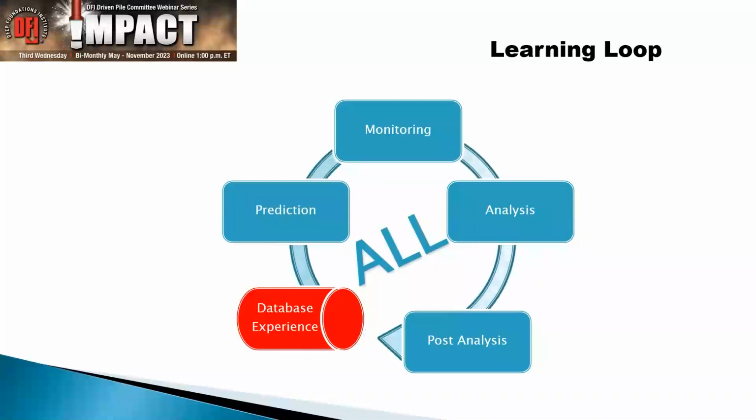Well, within Allnamics, we change it a little bit. We call it the Allnamics Learning Loop, but it's really nothing other than PDCA, but there's an additional step in there. And that is that red box that you see, where you now have your database experience. Basically, your plan is the prediction. Then you do it, and while you're doing it, you monitor your pile. Then you analyze those results. And you also do a post-analysis. You compare your assumptions before with your assumptions based on the analysis data, whether they're valid or whether they need to be adjusted. And then you stick that into your database, because that gathers the experience.